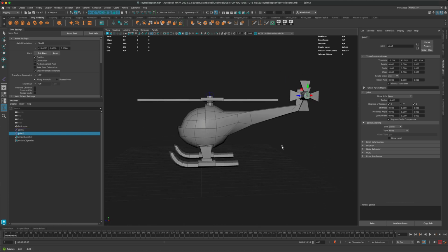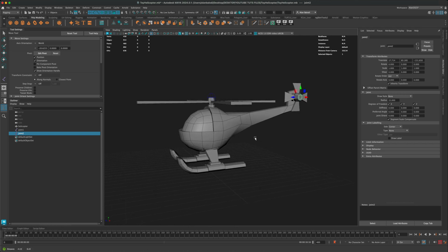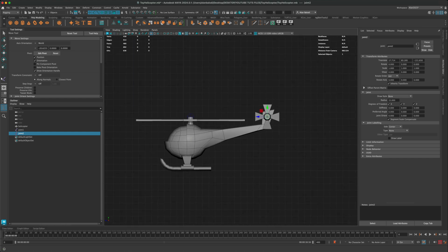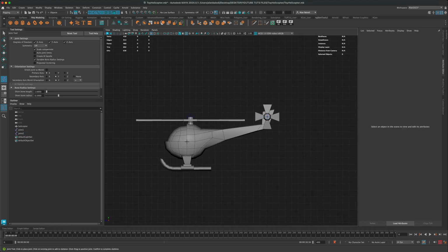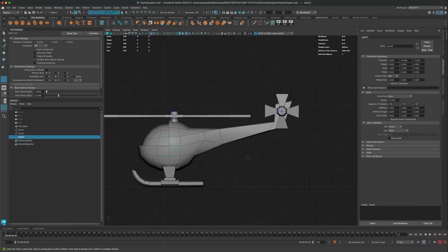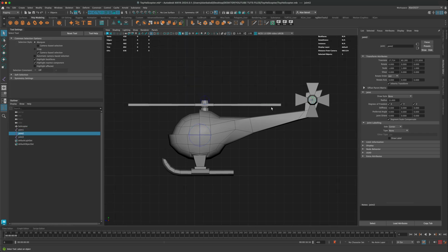Let's add one more joint that will be connecting them together, right? And the larger one will be kind of the body of the chopper. So again, I'm going to jump into my side view, grab my joints one more time, and place it maybe somewhere right in the center, somewhere right here. Let's go ahead and again turn the X-ray on so we can see our little dot. And for this one, I'm going to make it really large. How about 50? So something ginormous, right? All right, really nice. So now we have the base, we have the top, and we have the tail.